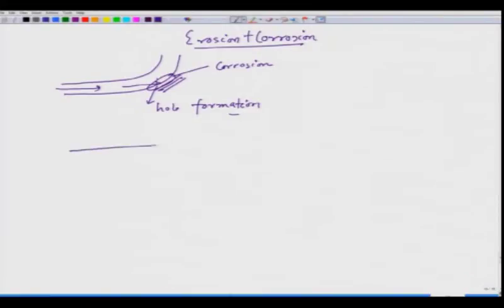If we have a pipeline design like this, the erosion corrosion tendency would be much higher, it will be felt more because of the effect of turbulence. If we have a flat section, a gradual change in slope or a corner, then the erosion effect would be less because the turbulence is avoided. This is a typical design aspect.